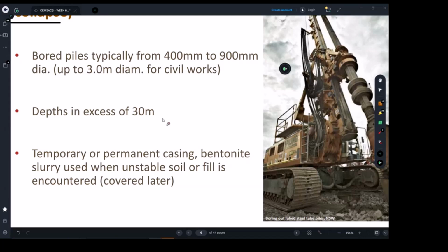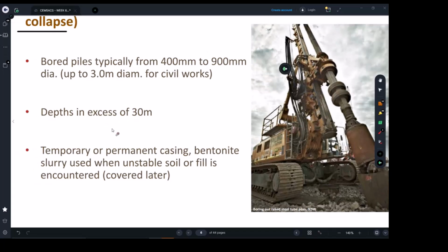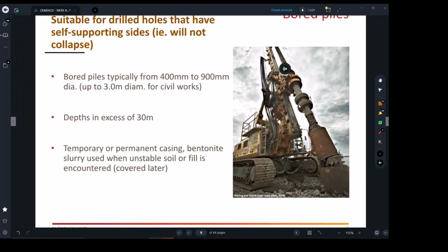And because residential properties are not as heavy as a tower, that movement I was talking about can actually move the house itself or the wall, and cause cracks in the building. So as a solution, the engineers will specify bored piers. And usually, as I was saying, for residential we're talking about 4 to 5 meter deep bored piers, not very much. And this would be the option to go with.